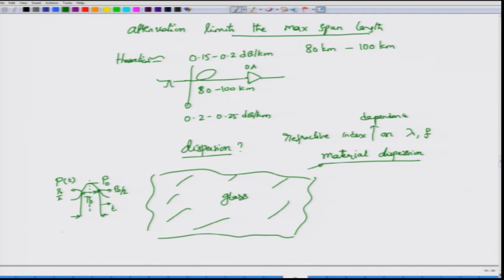It is normally called the full width at half maximum pulse width. Okay. So, this is very important. This is called the full width at half maximum pulse width. It is not the only definition of pulse width. There are various other definitions, but this is the one that is commonly used in practice to talk about the pulse width of optical pulses and what changes this pulse undergoes as it propagates through various optical elements.